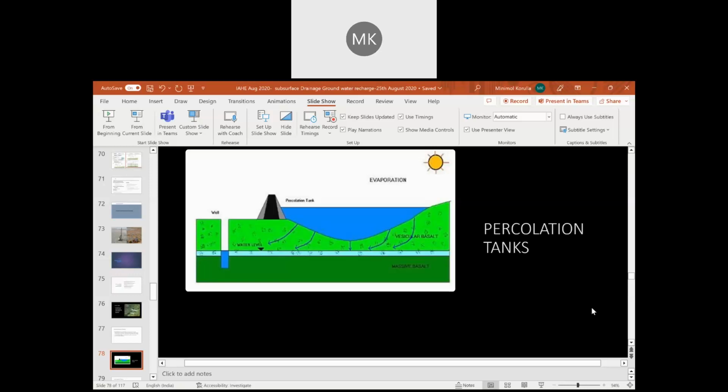So we have seen the hills, the different types of situations. And I think that in this course curriculum, you will be taught again by different faculties for different types of drains in hill infrastructure. So in hill infrastructure, the surface drains will be there, like toe drains or intercepting trench drains or catch water drains. Then there are gabion tube drains or cascade drains. All these are a part of the surface water drains.